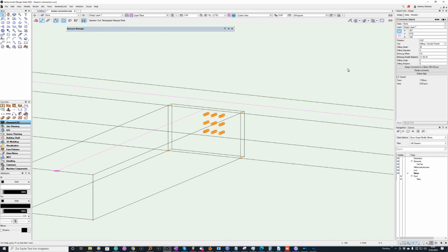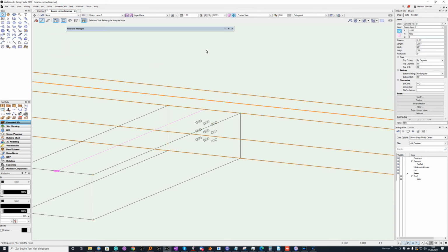And now I can make an offset in both directions, so I can put it not 300 but 30 millimeters or minus 30 millimeters. So I have the option to make explicit drillings with specific distances. I go to the actualization, and now I have the needed drillings.